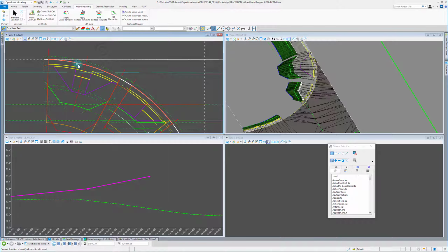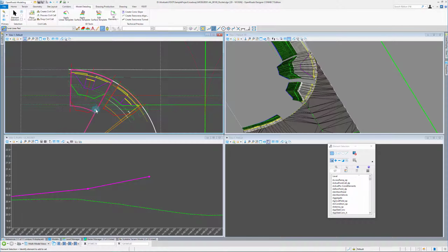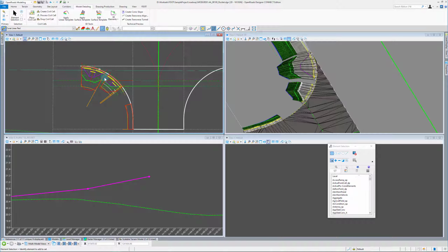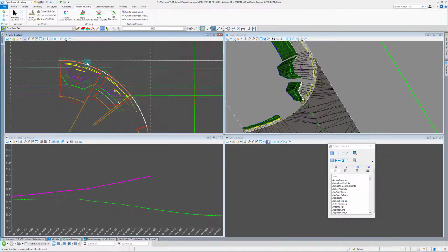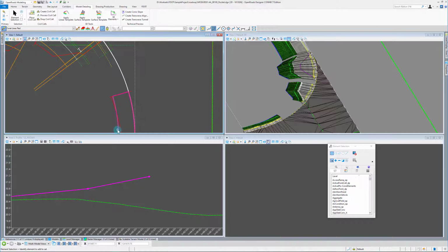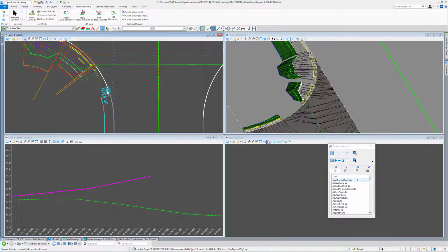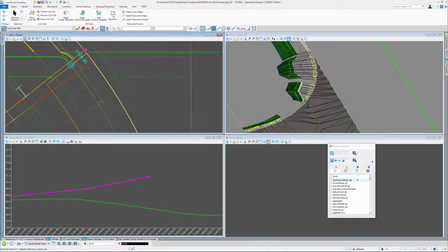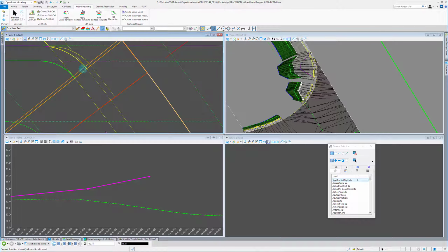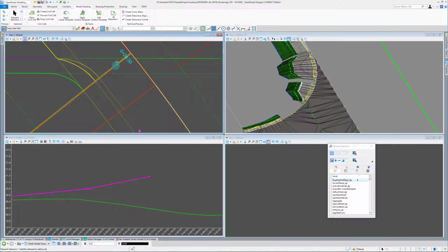So essentially what we have here is a couple corridors that have been placed along this line. I'm going to leave those corridors intact, and I'm going to come back and modify my original corridor. So I'm going to pull this template drop, and I'm just going to snap it to, there's a line underneath here. Am I in the right thing? Yeah. Should be a line there. Anyway, we can snap it to there.